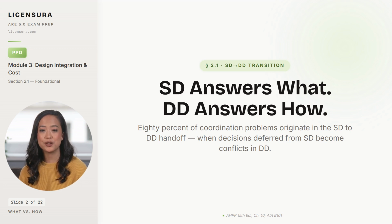Here's the uncomfortable truth most architects skip past. Schematic design and design development are not the same phase wearing different documentation hats. They answer fundamentally different questions about your building, and you confuse them at your peril. Schematic design answers what the building is: the big idea, the massing, the spatial relationships, the preliminary system types. Design development answers how the building works: how every system fits, how every connection details, how every element is sized and located in three-dimensional space.